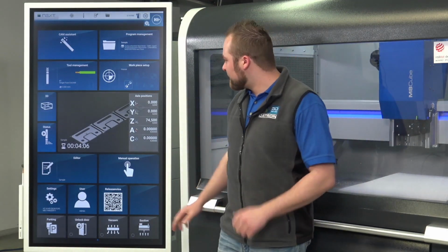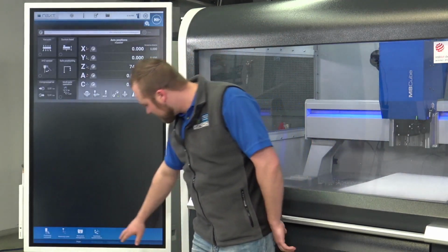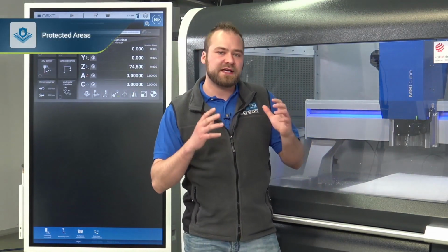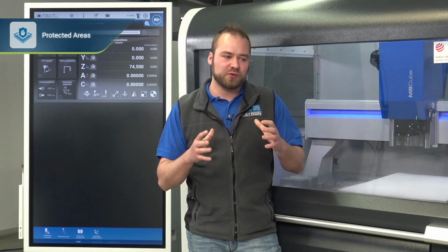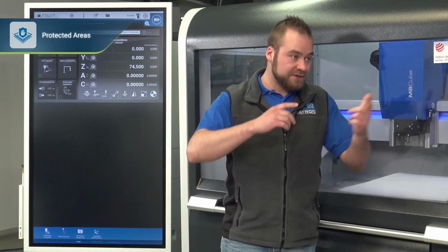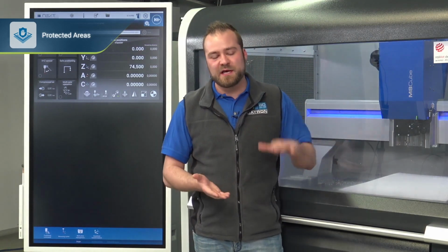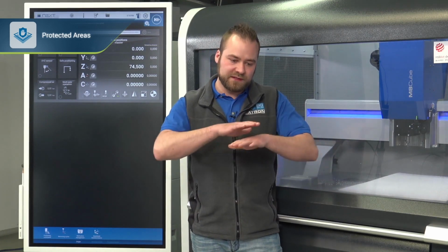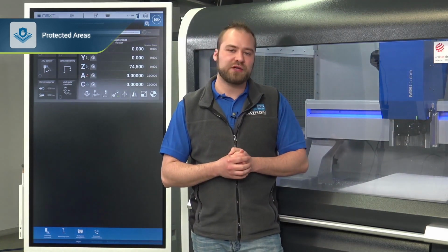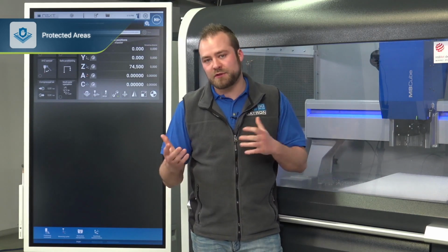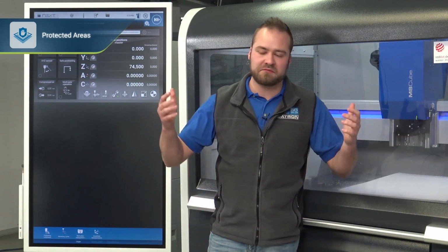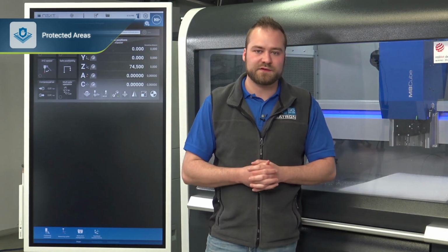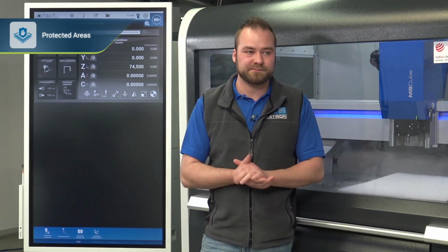So we can find here on the workpiece geometry, protecting areas. The protecting areas are there to protect your clamping system, and especially the vacuum. It is very easy, because we just have to set up a measurement point and set up the complete machine room for this. You can do this using a normal clamping system, and also the 4-axis. Right.